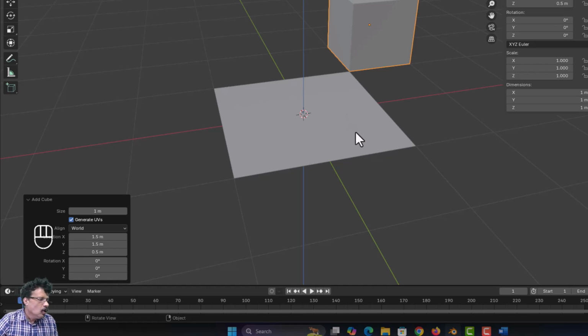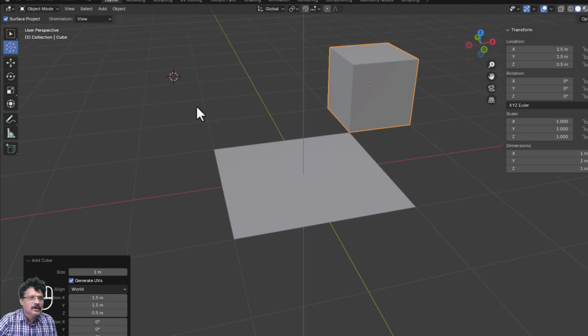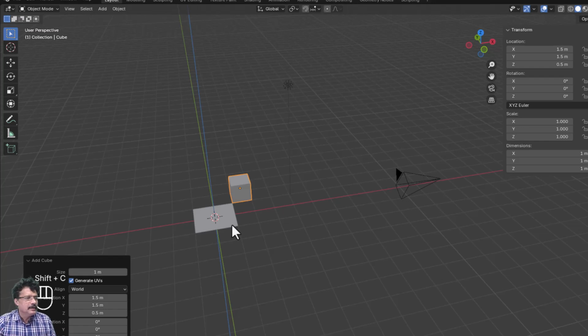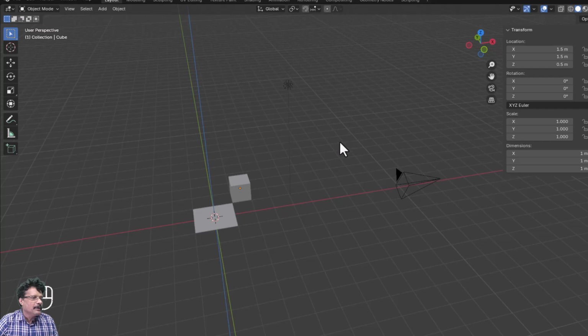Now if I click somewhere here, I take the selection tool. I was in the cursor tool, so I will take the selection tool and I will press Shift C again to bring the cursor to the center. If I do any other operation, so if I click somewhere and if I again select it, see this creation parameter disappears. You are not going to get it back.